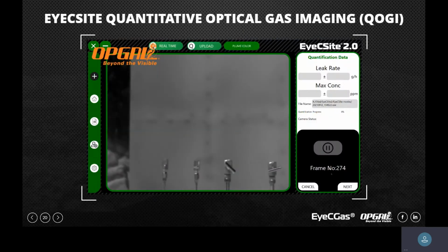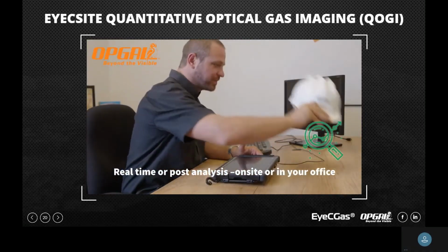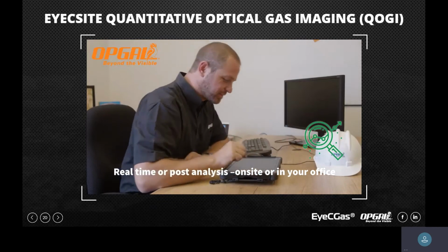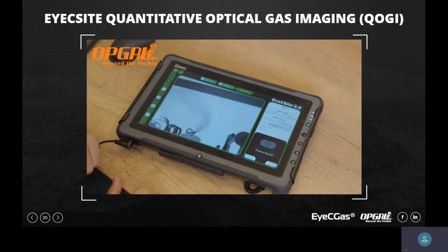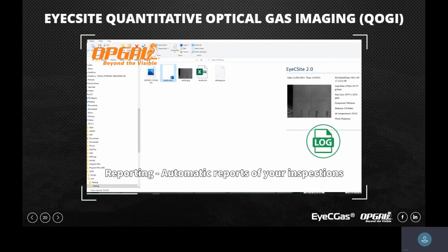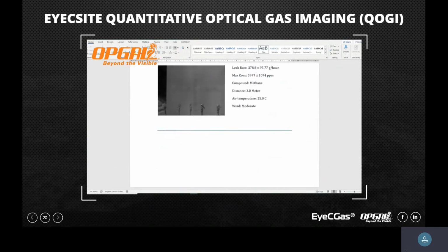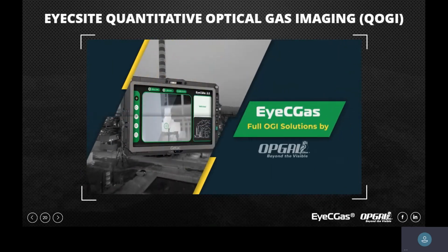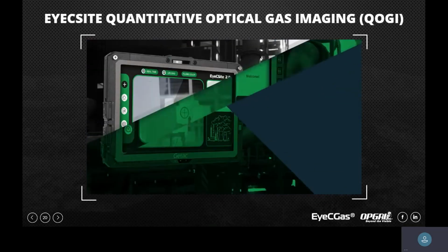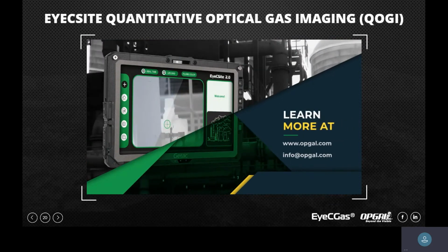But the reason I'm showing you this is that when we do quantification, we are really starving for sensitivity. And if we want to quantify alkanes, not methane, it's recommended to get better factors to concentrations by using the other filter. We get better sensitivity, so we can more accurately quantify when we get very close to our detection limits, either because of the environmental conditions or a small leak.